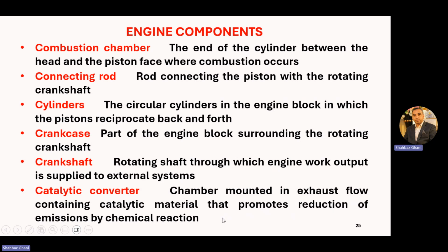Remember this thing, when there is a combustion, it is not ideal. It is not 100%. So there is an emission problem. We have NOx, carbon monoxide, and excessive carbon dioxide. So this catalytic converter reduces those emissions by chemical reactions and gives a clean exhaust.